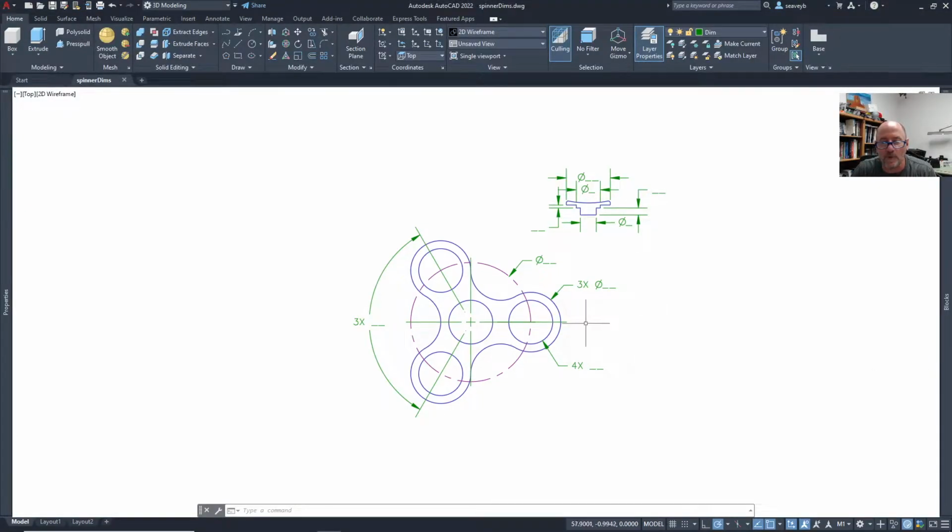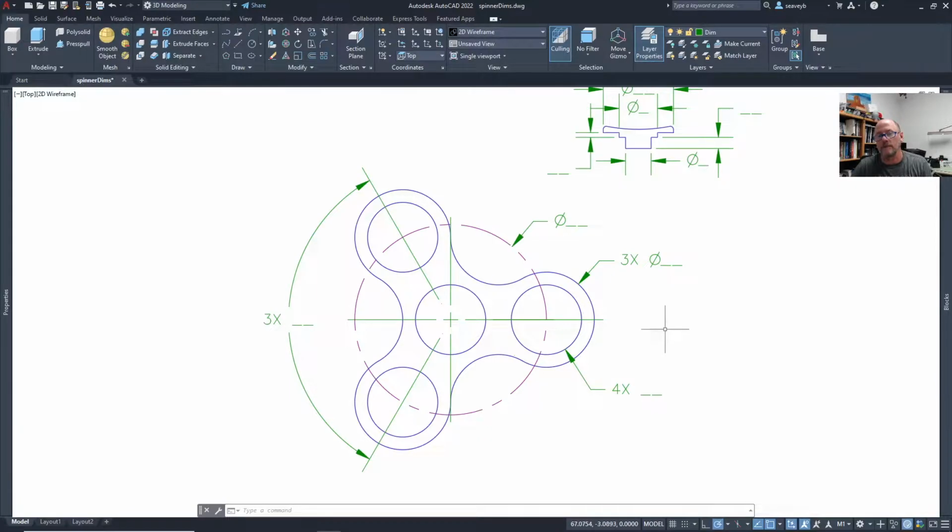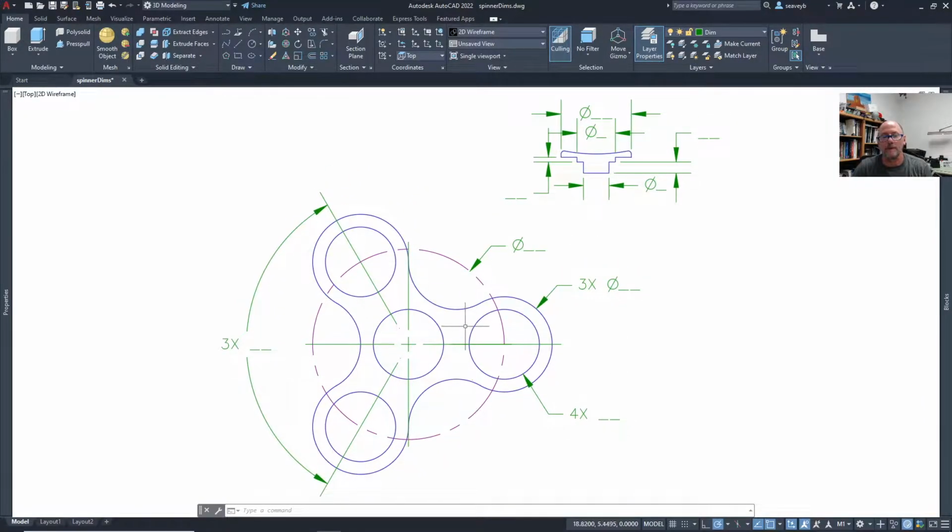Okay, we want to make a fidget spinner. We'll use Blender. I wanted to look at the dimensions of the spinner. Given a 608 bearing, the outer diameter of the bearing is 22 millimeters, and I wanted a 4 millimeter thickness of the plastic, so that ends up being, well, 15 millimeter radius on the outside here.